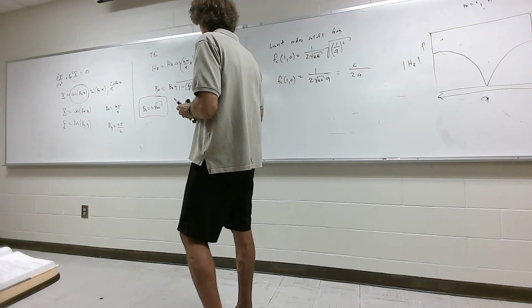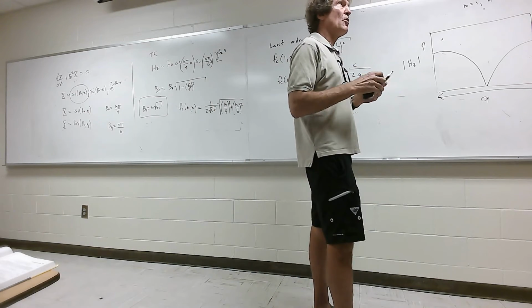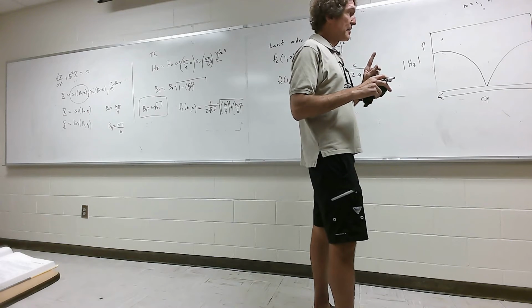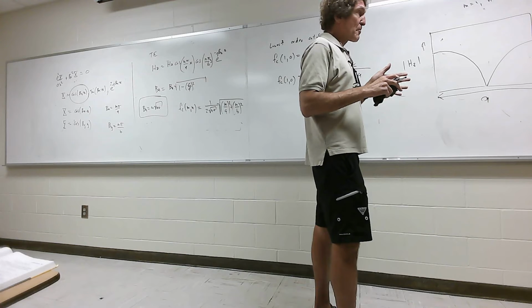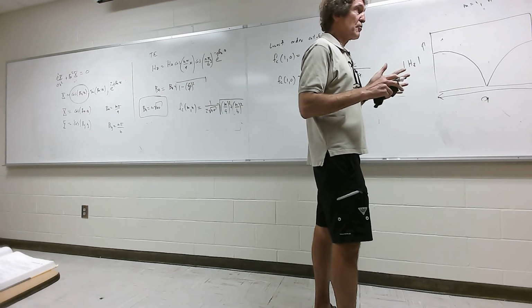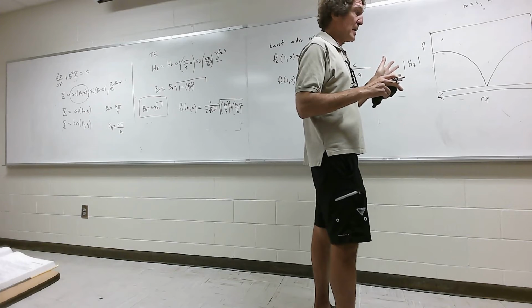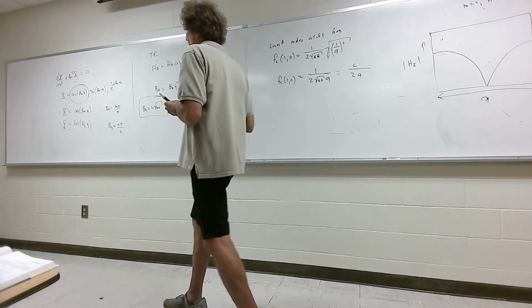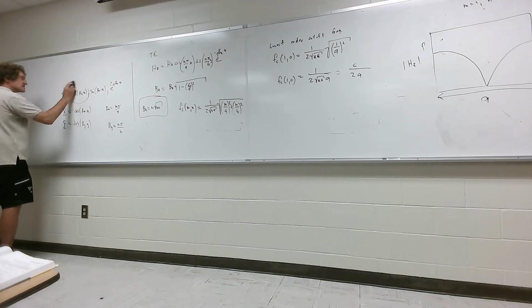That's normally the way it's done. Almost all waveguides that are rectangular operate in a 1,0 mode, where their operational frequency is probably about 2/3 of the way between the first cutoff and the second cutoff mode. I'm kind of hedging like that too, because I'm thinking of some special cases, but that's about right.